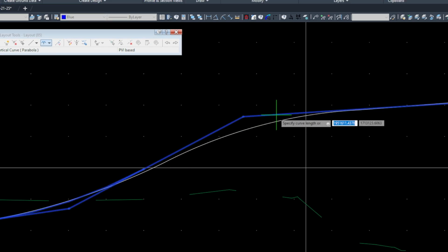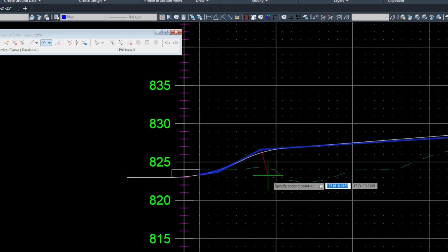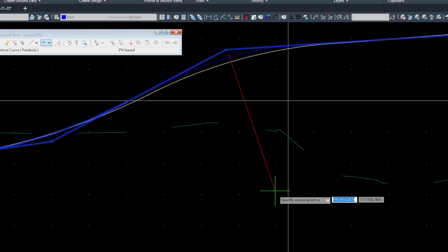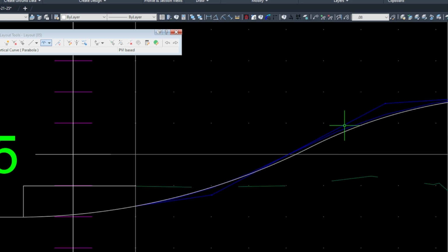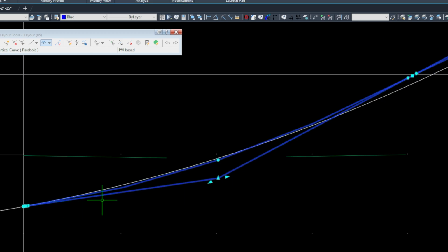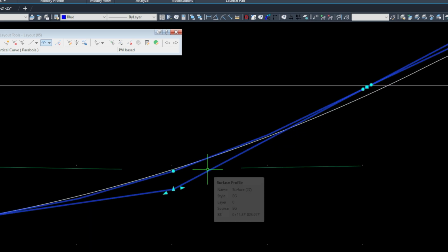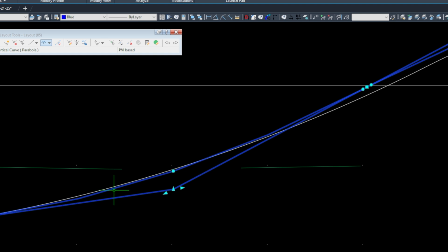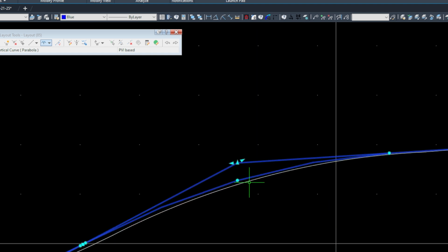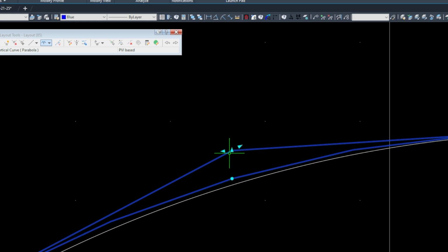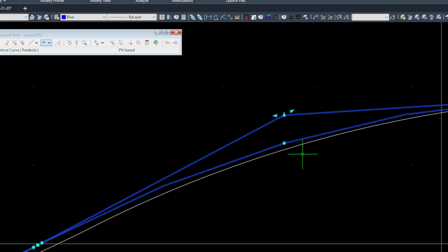and then I'm going to do the same thing, select both of my curves, and then I'm going to click and drag as such. Okay, whenever you draw your curves in, you're still going to see the straight lines and then your tangent point here. That's not actually where, when your corridor references your vertical profile, it's going to draw on the surface along the curve here. So try not to get confused by these straight lines continuing past the curve and meeting here to make a vertex. That's not where your surface is actually going to generate. It's going to generate along the curve here.